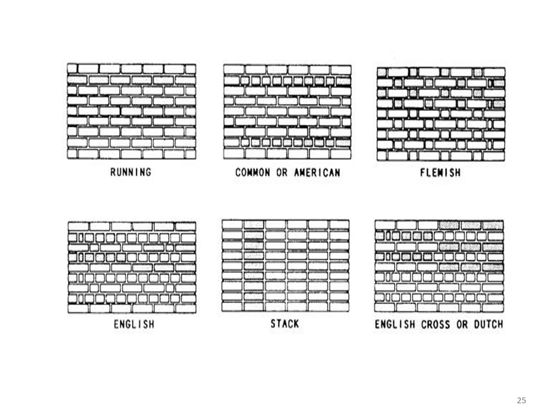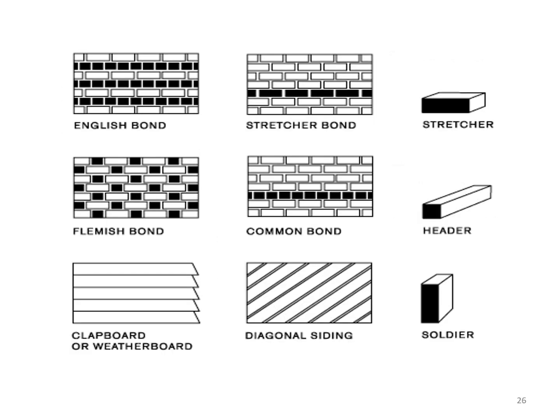Like I say, take a look at brickwork or masonry. At one point you'll see, oh my gosh, all the buildings, they don't all look the same. They all have these different items. So again, now looking a little closer at the English and the stretcher bond, and why it's called a stretcher is because you use the brick, a long brick, that's called a stretcher when you're using it the long way. And the other type is a header. That's usually to bond between 2 rows of brick. Now for architectural reasons it could be just sometimes a piece of brick placed in there, but here we have those special headers that connect between the 2 rows of brick or an inner row of any other item.